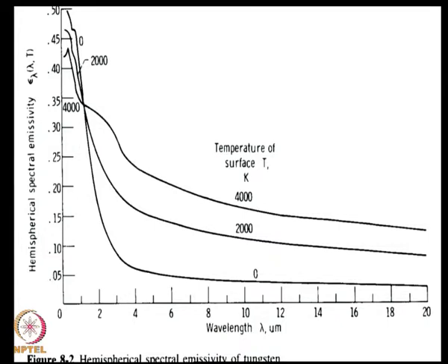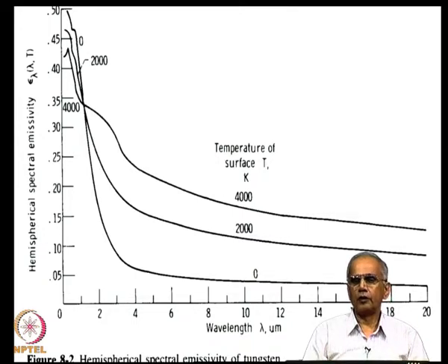So, whether you make a gray surface approximation or not depends on the accuracy demand in a given situation, and that can vary a lot in a real world situation in engineering. In certain field conditions, one would not mind a 30-40% error if one wants a rough estimate of the heat flux.